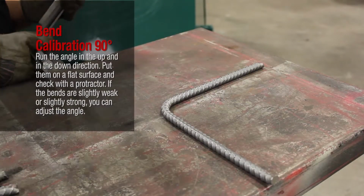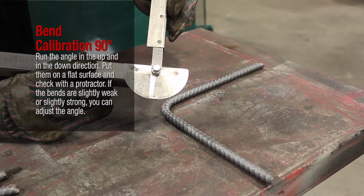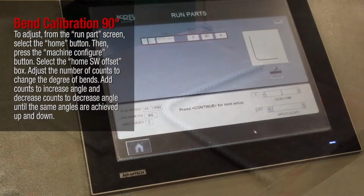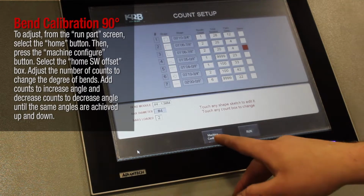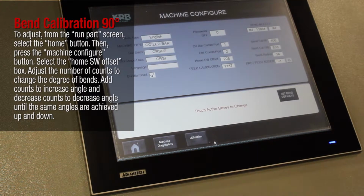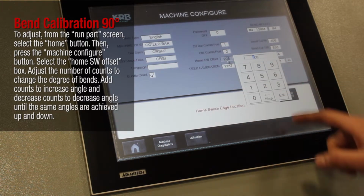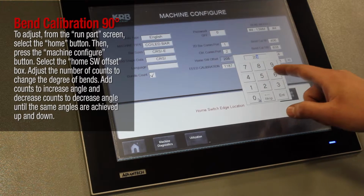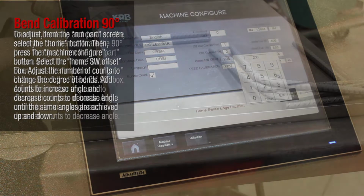Put them on a flat surface and check with a protractor. If the bends are slightly weak or slightly strong, you can adjust the angle. To adjust, from the Run Part screen, select the Home button. Then press the Machine Configure button. Select the Home SW Offset box. Adjust the number of counts to change the degree of bends. Add counts to increase angle and decrease counts to decrease angle until the same angles are achieved up and down.